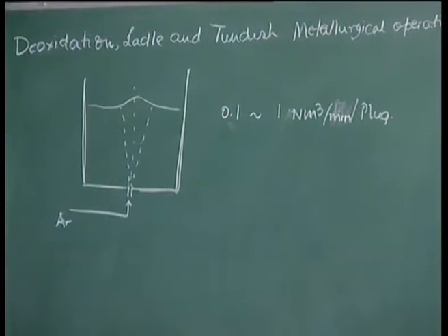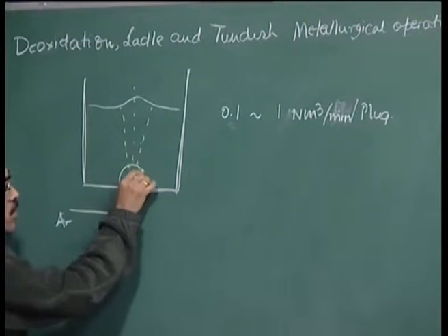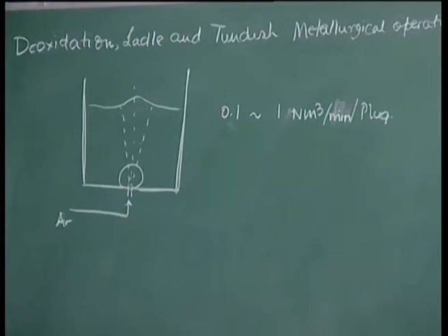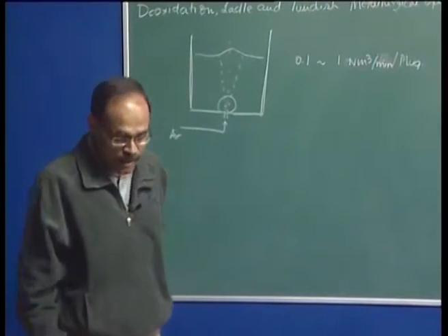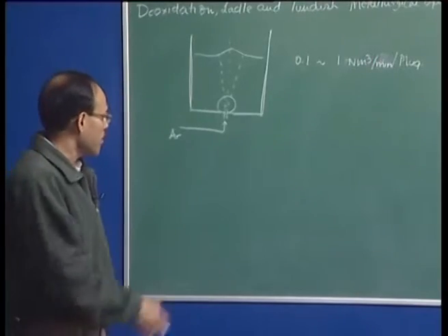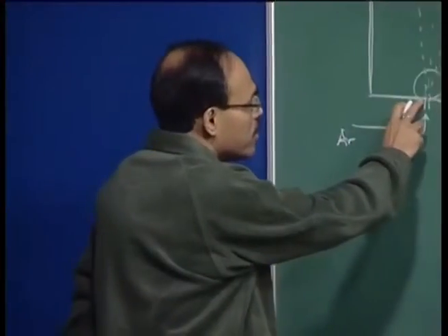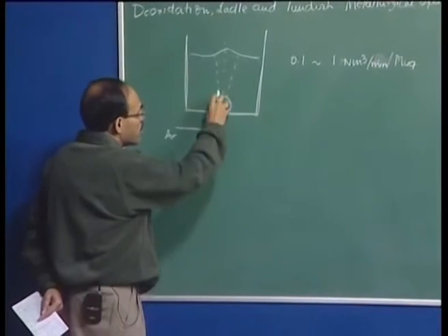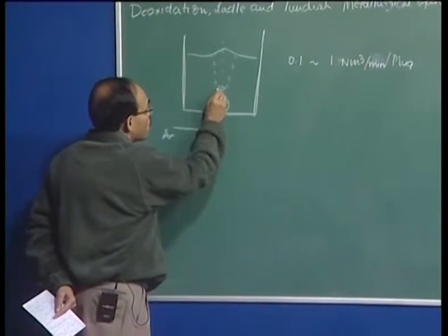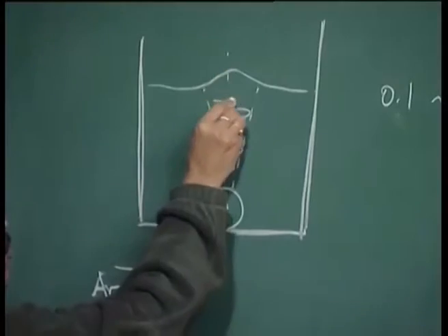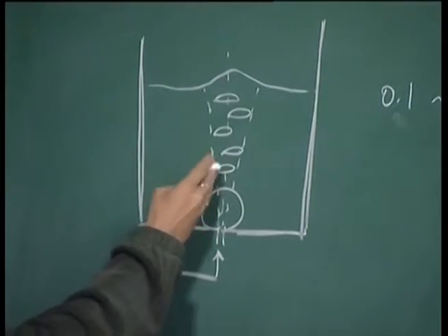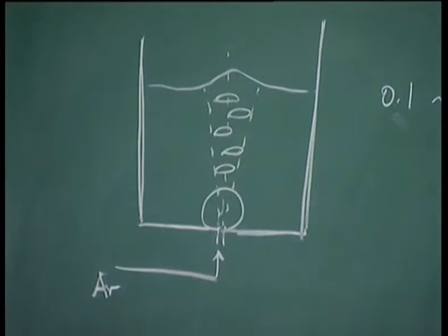Now, under the ladle metallurgy gas injection operation, when we inject argon gas through a nozzle, typically a big gas envelope forms in the vicinity of the nozzle. This gas envelope is typically hydrodynamically unstable. The fluid cannot really sustain that big a gas envelope. So, immediately above the gas injection nozzle, this big gas envelope typically devolves into a spectra of spherical cap bubbles, and these bubbles then rise due to their buoyancy and escape to the surrounding.